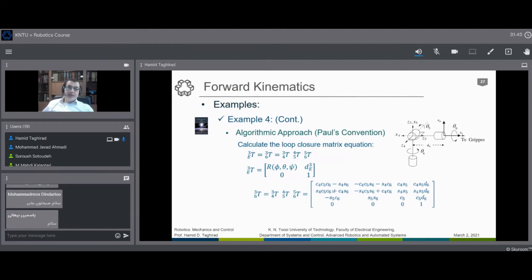For forward kinematics, we don't really care about that. What we have is a one-to-one correspondence between 3 angles here and 3 angles here. If you use these 3 angles as the right Euler angles, you can easily find phi, theta, psi from that. But if you use another form of Euler angle, then these relations are not very simple to be found in terms of inverse kinematics.